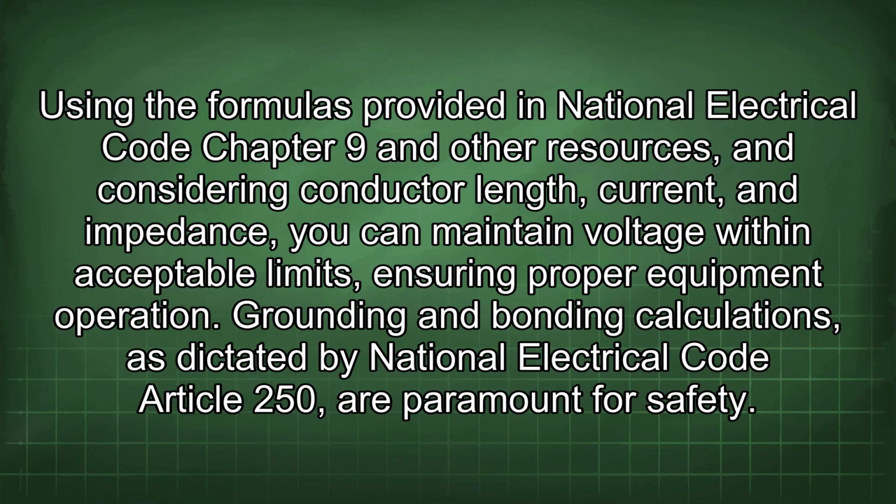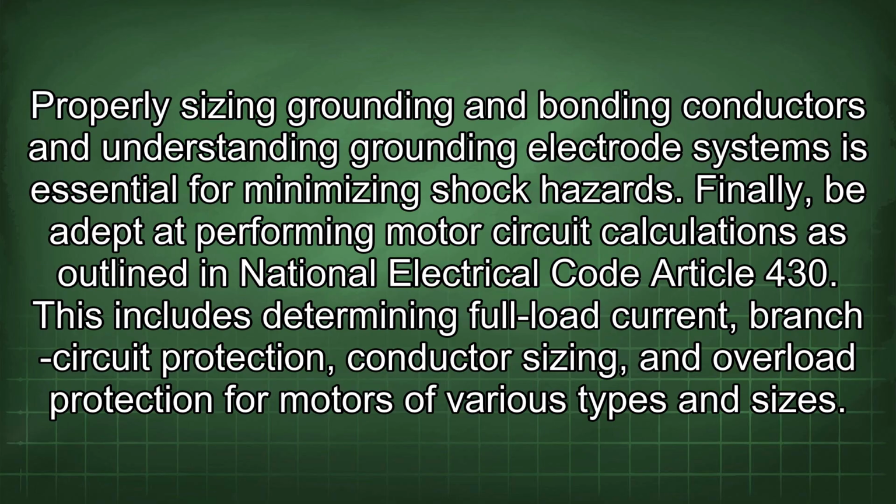Grounding and bonding calculations, as dictated by National Electrical Code Article 250, are paramount for safety. Properly sizing grounding and bonding conductors and understanding grounding electrode systems is essential for minimizing shock hazards.